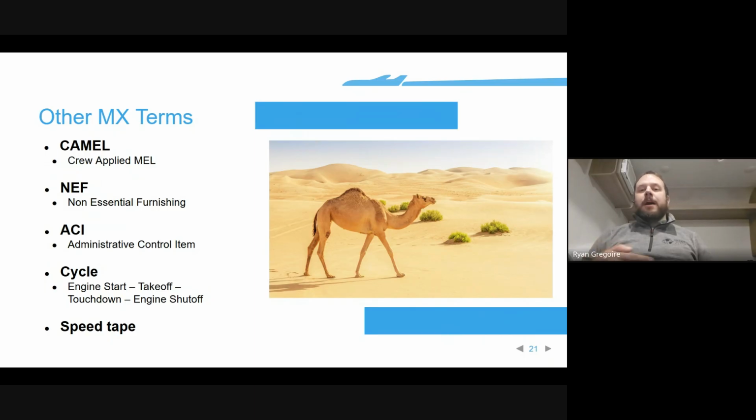And since you're not the person who is controlling the maintenance side of the aircraft, that has to go to someone who is, because you don't know if it's something that should be there that isn't there, or it's something that isn't there that should be there. But everything needs to line up between what is applied to the aircraft and what appears on the dispatch release.